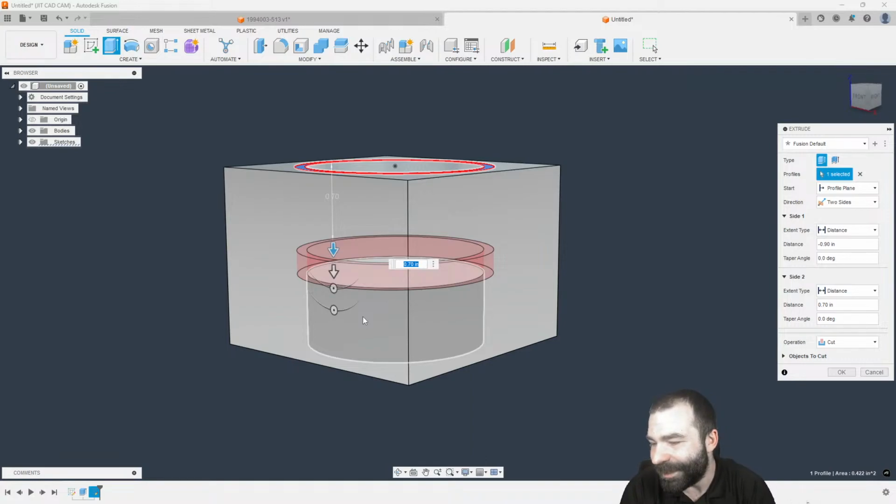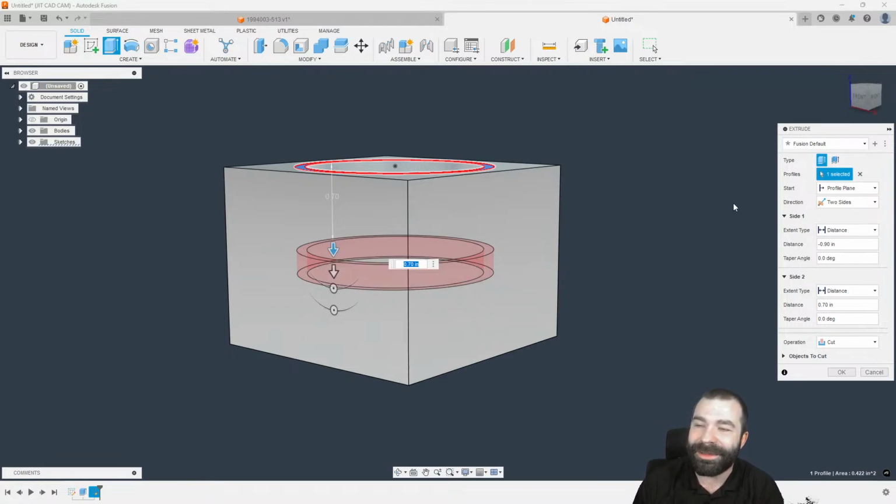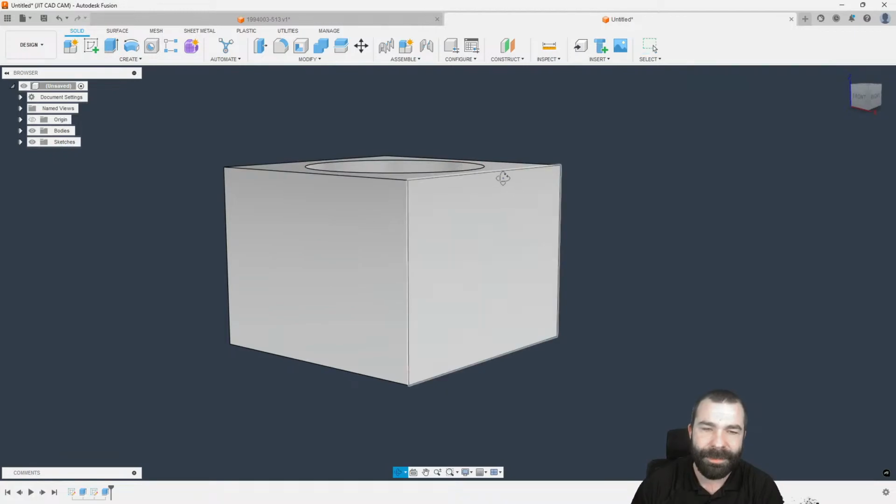I always have to mess with the top height of my groove when I'm milling with a slot cutter. I've got a little bit of a secret there for you. I see probably the quickest way is to use two-sided extrude. 100%. As you're seeing me do, I am doing exactly that. We did two-sided so that I could place that groove wherever I wanted it in my part.